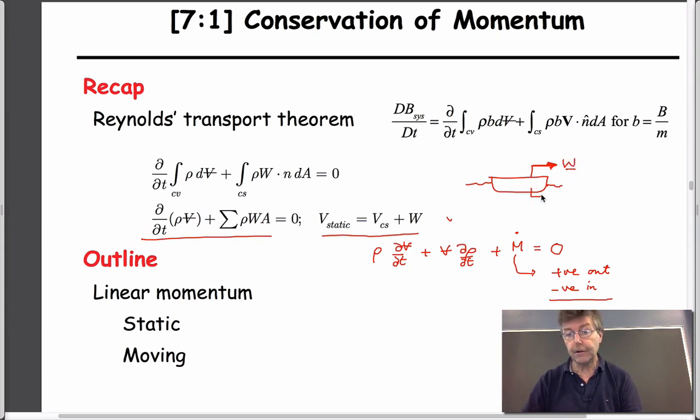The velocity of the boat is the velocity of the control volume. And the velocity of someone standing on the quayside watching this is the observed velocity of the whole system relative to the static reference frame. So not the velocity of this person, but the velocity at which he views things. If the boat is flying water at 1 meter per second, and the control volume is moving at 2 meters a second, then the static observer sees this at 3 meters a second.